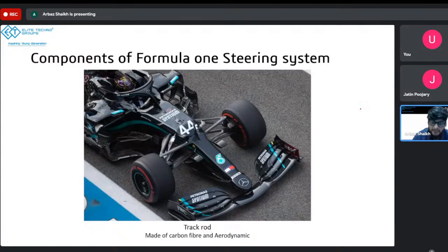And one more thing, in this picture you can actually see the push rod and the tie rod differently. Here's your push rod, and this is your upper wishbone. This is the push rod once again. This is the upper wishbone, and this part is the lower wishbone, and this rod just coming out is your tie rod. Over here you can see the cross section of these rods. They are flattened to be more aerodynamic. So that's all I wanted to talk about these things.